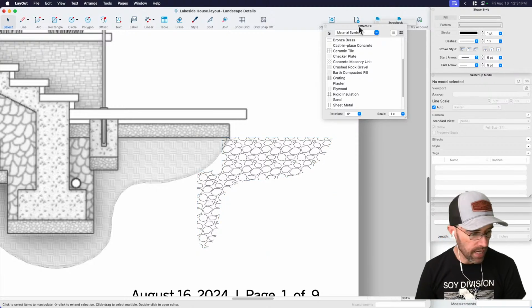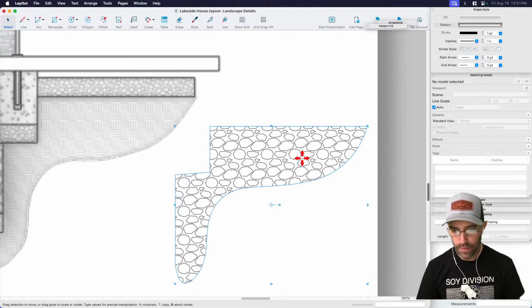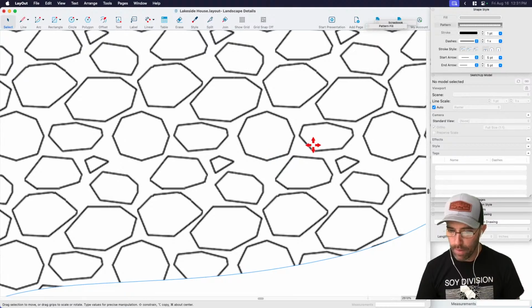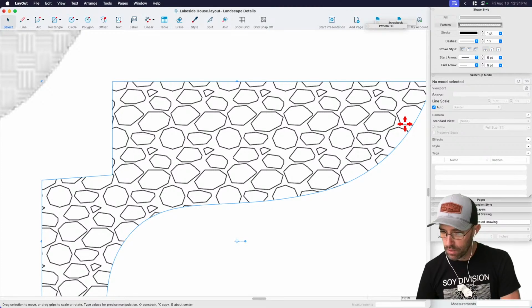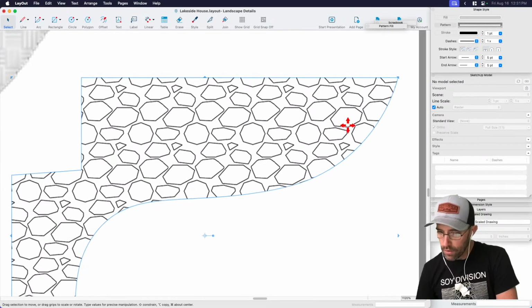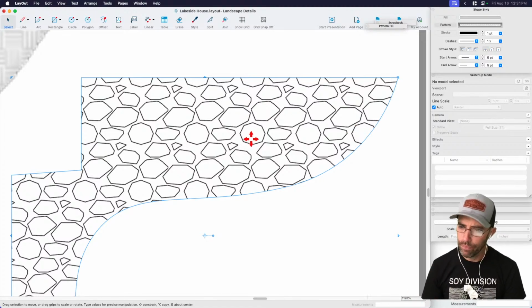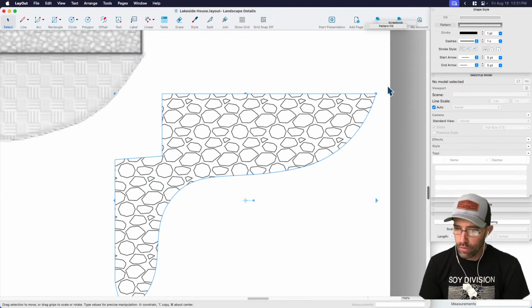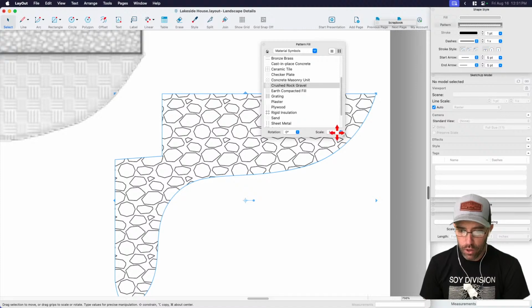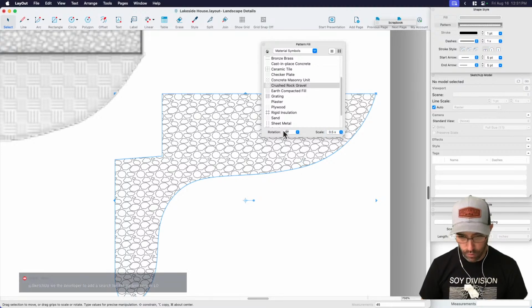What somebody was saying earlier is that when I zoom in, these patterns are also raster, aren't they? Is it because your display is set to raster? No, because scaled drawings are raster by default. So this is actually pulling an image. Okay. But the cool thing is that you can have more control. For example, under pattern fill, you can change the scale. So if this scale is too big, I can go 0.5. Or if I wanted to rotate it, I could just really simply go 45.